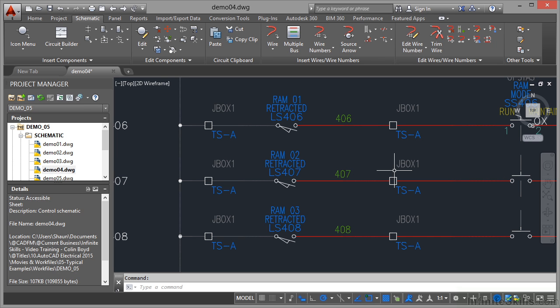You must use the editing tools in AutoCAD Electrical though. This is all linked to the AutoCAD Electrical database, and you must use the tools provided. Don't just go in and use the AutoCAD text editing tools to change a wire number or a junction box number. And don't explode the blocks either, because they are all linked, automated, with parametric tools and block attributes and so on. The whole idea of this is to make your life easier. You will make your life much more difficult if you explode things in a typical AutoCAD electrical drawing.